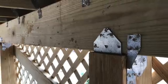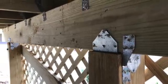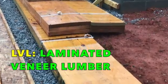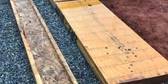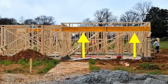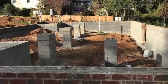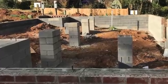Girders and beams are sometimes made of dimensional lumber grouped together. Or more commonly, they're made from LVLs, laminated veneer lumber, a type of engineered plywood that is very strong and comes in really long pieces so that they can bridge longer spans. Now, girders and beams also need something to sit on for support. Sometimes they rest on masonry piers, like in a foundation. Other times, they rest on columns or posts.